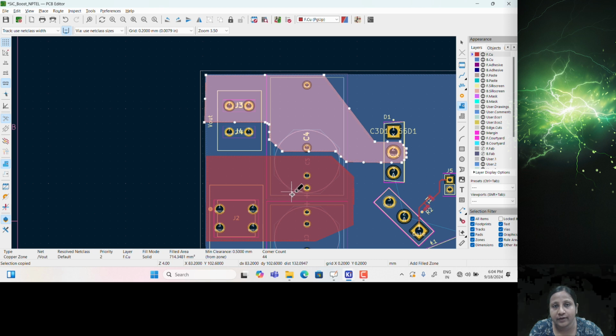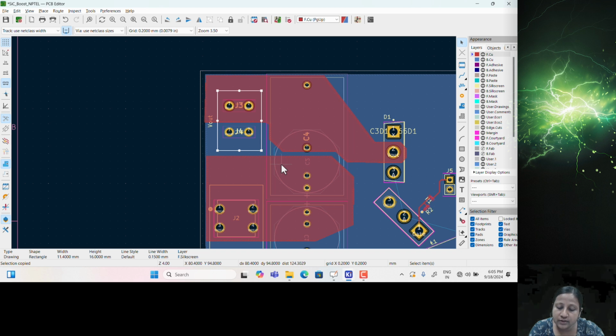In a similar way the ground reference is connected in this red portion. Here all the points related to ground are connected, the entire shaded portion. You can just use a simple wire or you can show it as a shaded portion, right? The entire red portion here is V out. All the pins belonging to this are connected together. So that is why you can keep it properly, so that you can give a particular area for that particular V out or the ground reference. It will reduce the noise in the PCB.